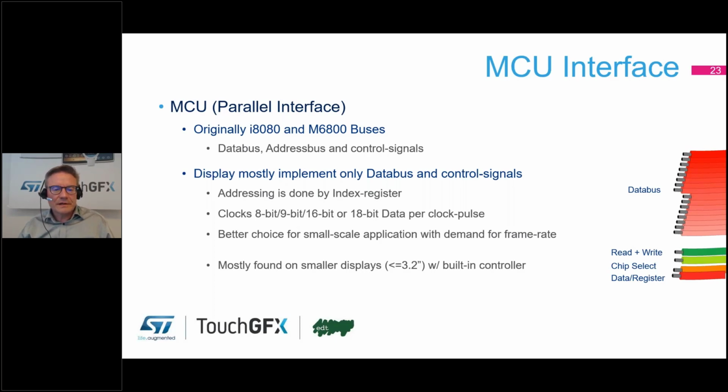The MCU is a very nice feature. It actually has a small graphic controller built into it, and it has some memory, so you can upload the pictures to the memory and fire them off when you are ready to update the display, so you don't have to constantly bit bang the data bus. Or you can simply tell the controller to update a small portion of the display. You don't need to update the entire frame. So that's a very nice feature actually.